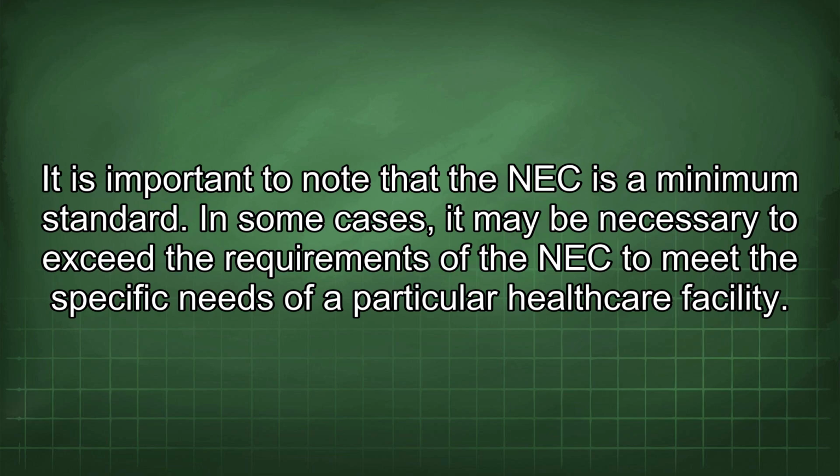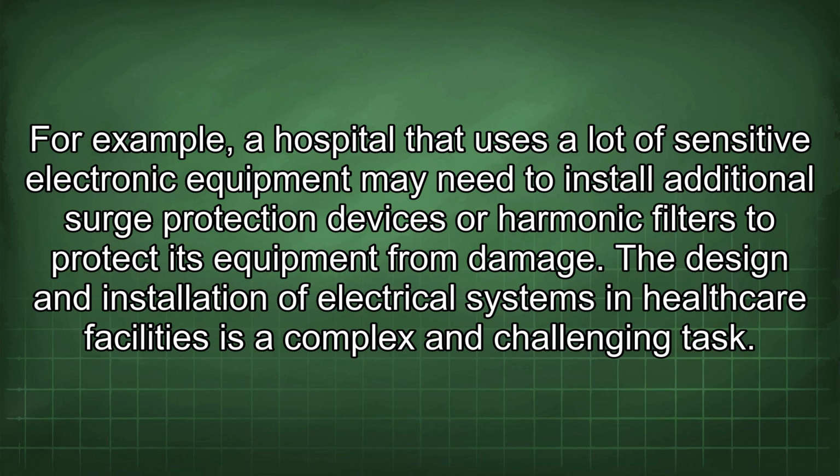It is important to note that the NEC is a minimum standard. In some cases, it may be necessary to exceed the requirements of the NEC to meet the specific needs of a particular healthcare facility. For example, a hospital that uses a lot of sensitive electronic equipment may need to install additional surge protection devices or harmonic filters to protect its equipment from damage.